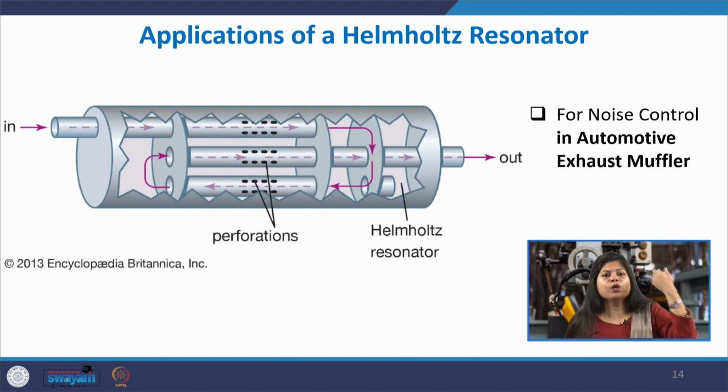The whole operation of the IC engine within an automotive system is synced with the frequency at which the engine is operating. So whatever noise is created because of the operations of the engine, be it combustion noise, exhaust noise or anything else related to the engine, the sound waveform will be such that the noise peaks at some fundamental frequency corresponding to the frequency at which the engine is operating. So, the sound will peak at the engine frequency and its higher harmonics.